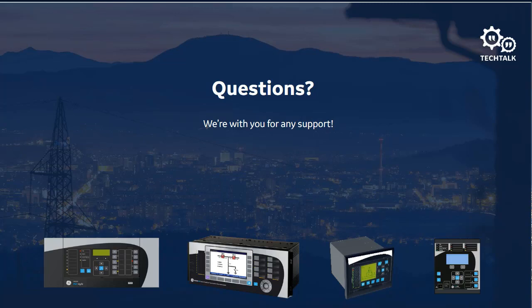But in this case, since we're trying to solve a 3-variable problem with a single variable, if we want to do this, we're going to have to make some intelligent assumptions. One of the things we can do is, if we know the fault type, say a phase to ground fault, and we're given the positive sequence current, we've also been given the negative and the 0 sequence current, because those 3 are in phase.